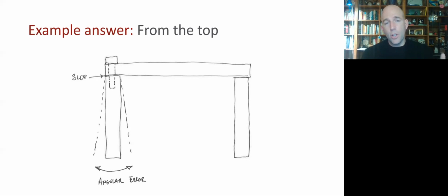And just taking a look, that's going to be a big number. And so a little bit of manufacturing error or something like that here is going to lead to a pretty big error in the angle of that plate and the axial location of the bearing, and also possibly the angular orientation of the bearing. And we've seen stuff like this in our project 2 components, where a little bit of defect in that surface would cause the thing to tip in some undesired way. So it's a similar thing.